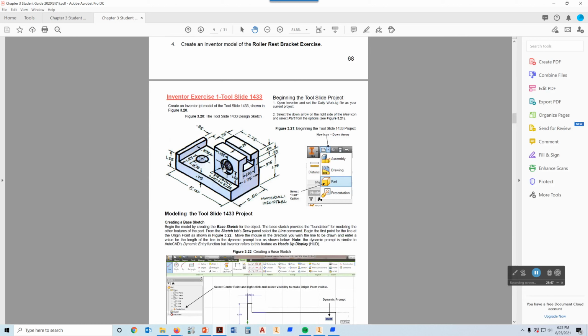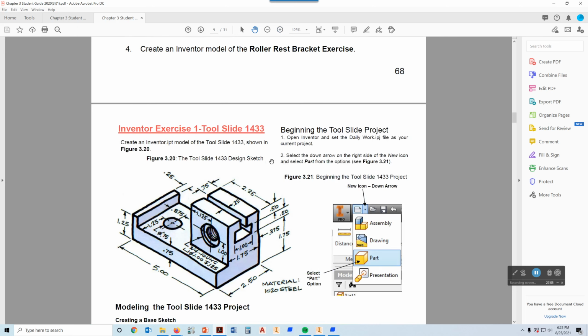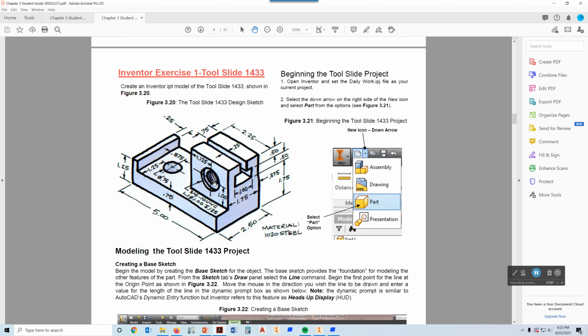But look right here, we have another hole on this vertical plane. And this one is 1.125 from the left-hand side. It's 1.0 from this edge right here, 1.0, 1.125. It goes all the way through, but it's a little bit hard to read this note. So let's look at this.